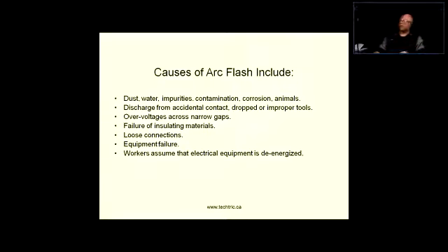Not only are you going to disconnect that, you also are supposed to make sure that that circuit breaker or disconnect cannot be flipped back on by accident, by somebody who's just thinking, oh, why is this thing off? It should be on, right? So there are lockout procedures or there are attendants involved. The best way would be a lockout mechanism with tags and an attendant, just someone who stands there, making sure that nobody even tries to turn that thing on. If something is around the corner or further away, the best thing is to have an attendant.